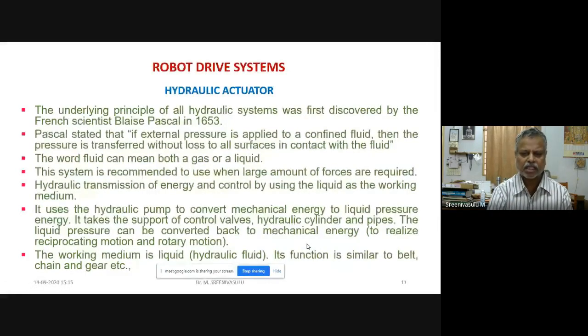Once you have a cylinder and piston arrangement, you need to have inlet valve and outlet valve. Inlet valve is to bring the fluid, collect the fluid between the cylinder valves and the piston. Soon after that has been trapped, inlet valve is going to be closed and the piston is going to be moved forward or close to the other end, so that fluid is going to be pressurized. Once the fluid has been pressurized, outlet valve is going to be opened, then that's going to be delivered.